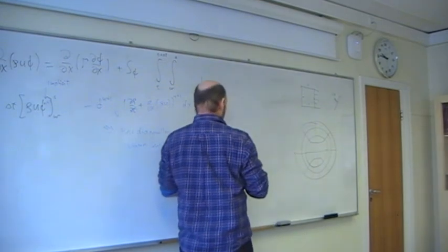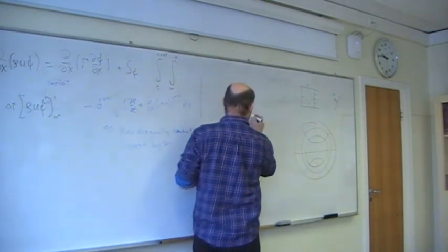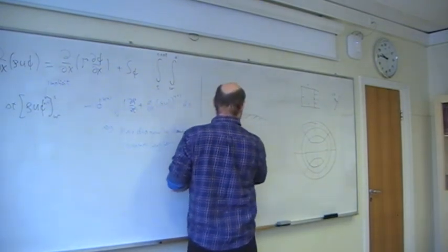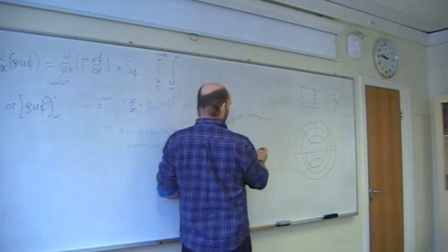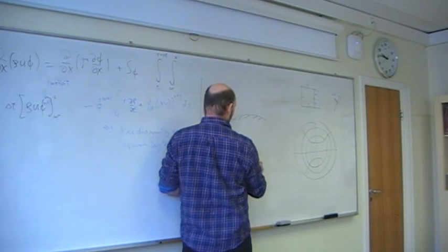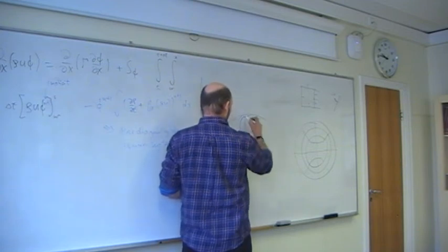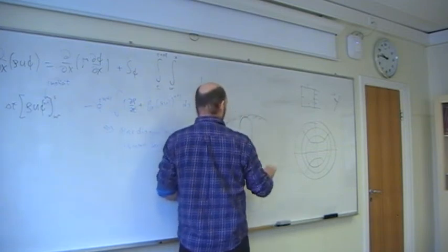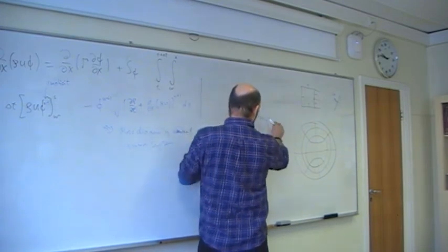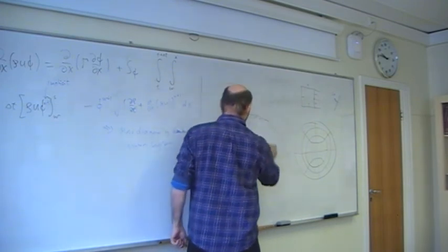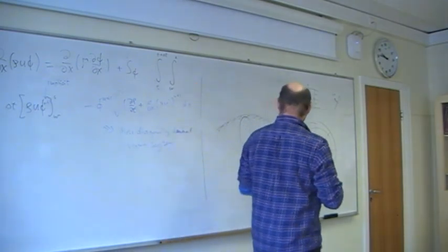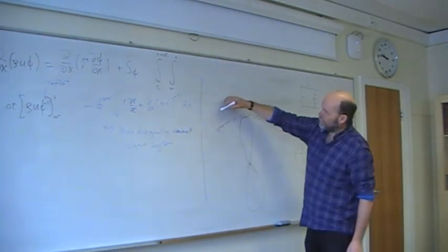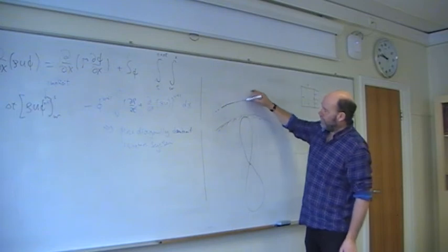Because what you do then is to create one mesh system here, say following the thing that rotates, say if it was a turbine or something. So you create one mesh in a circle around the rotating object, and then you have another mesh outside which now is fixed.